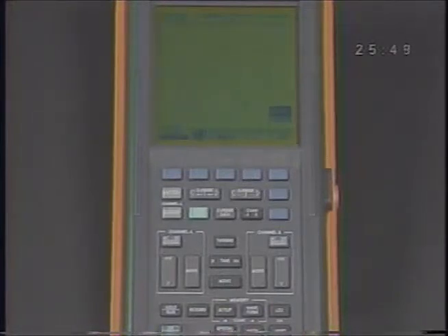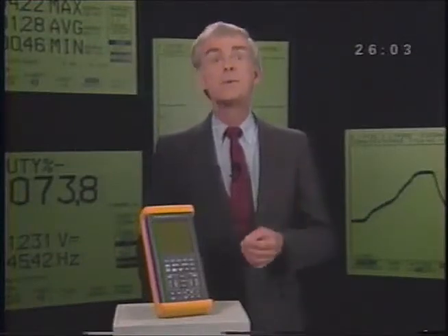But without a trigger level, Scopemeter doesn't know when to begin to trace the waveform. The starting point varies, making the waveform appear to wander. Trigger allows you to decide where the waveform begins, so you can view a waveform in the form that makes it easiest to read and diagnose. Adjust the trigger on your Scopemeter to 0 with a positive slope and move the waveform back to the edge of the display. Then you're ready to save your setup.